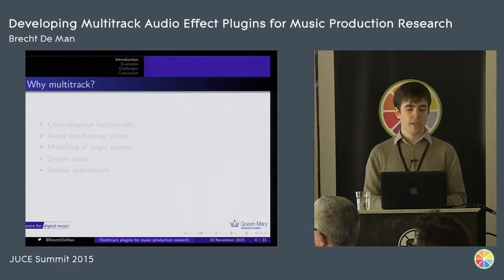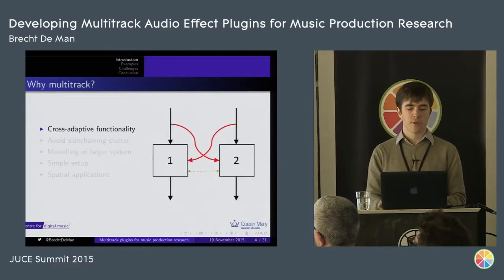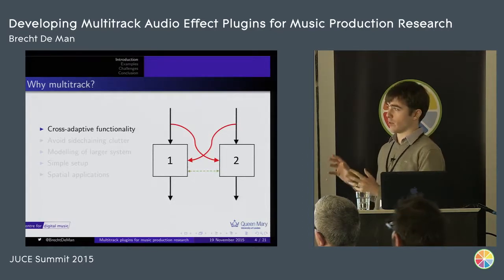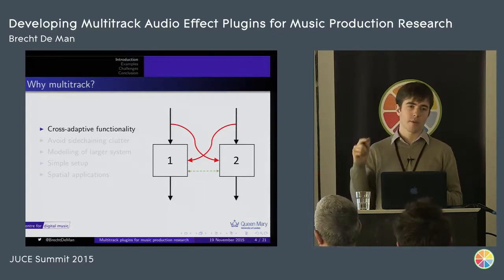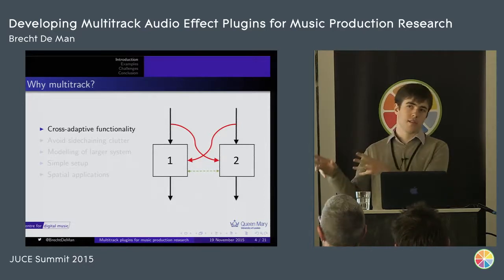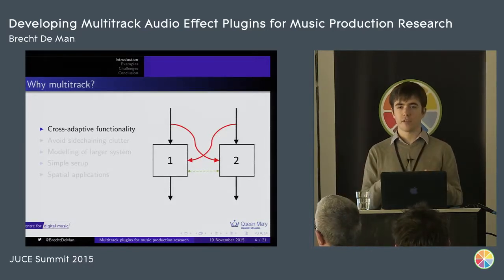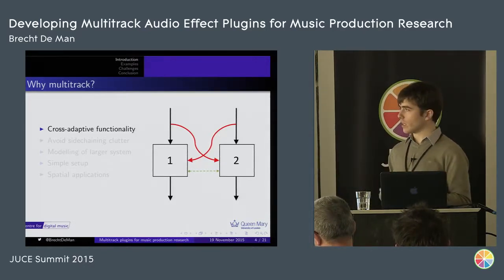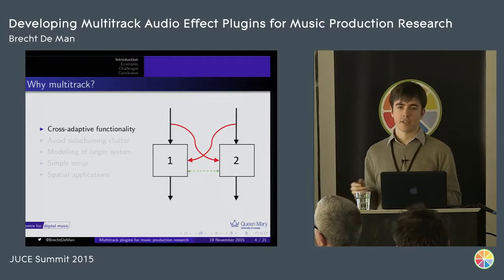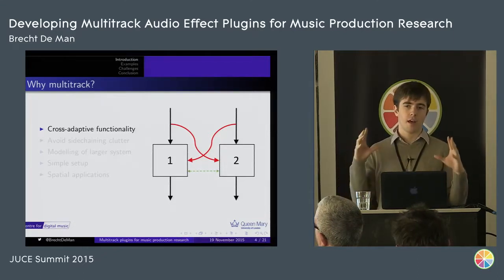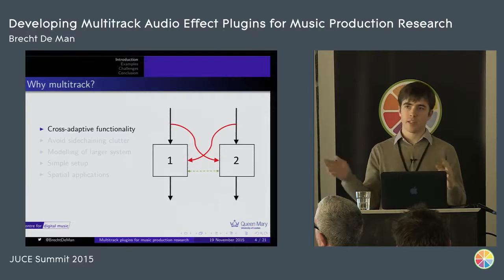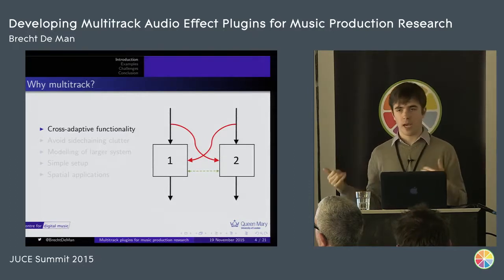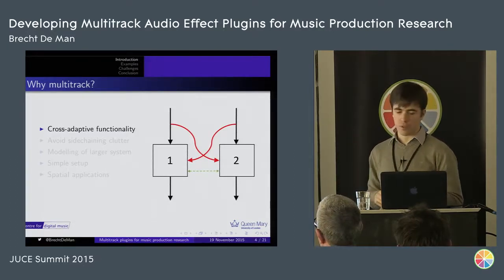So why would you ever want to make a multitrack audio plugin? First of all, if you're interested in some kind of cross-adaptive functionality where maybe the processing of track 6 depends on the audio features extracted from track 1, then such an architecture is quite hard to make unless you have a plugin that takes many inputs at the same time and maybe outputs a lot of audio streams as well.